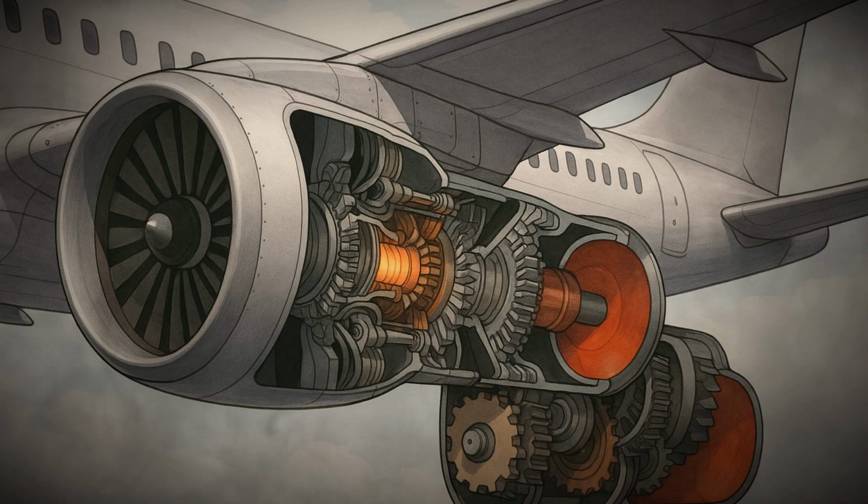Shorter, broader wings with lower aspect ratios produce more lift at lower speeds, which is useful for fighter jets and aircraft that must operate from short runways. Some aircraft employ variable geometry wings or flaps that extend to increase the surface area and angle of attack during takeoff and landing, enhancing lift when it is most needed. These adaptations reflect how the physics of lift is applied in practical engineering solutions.